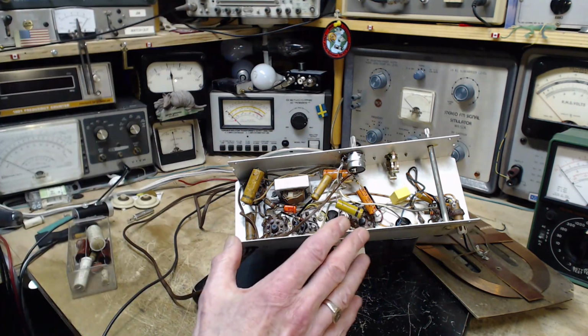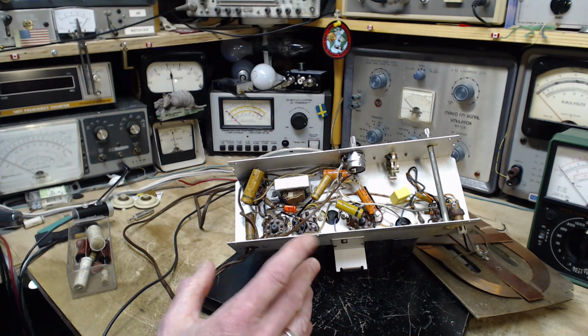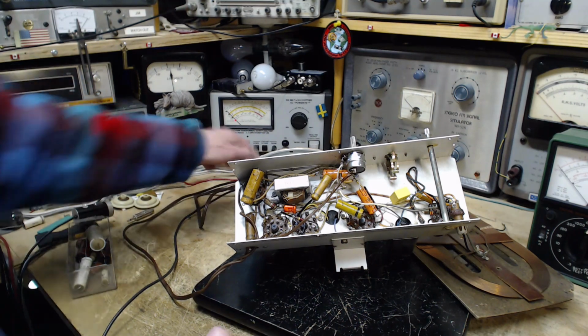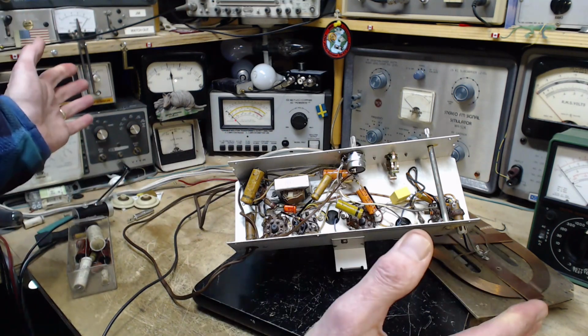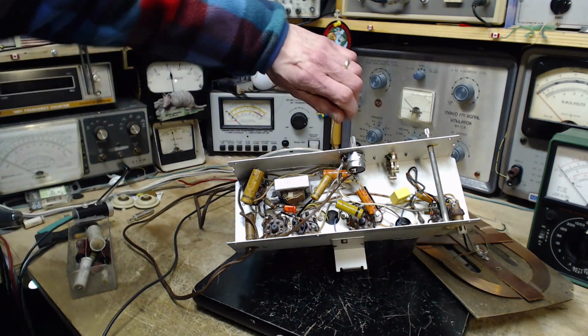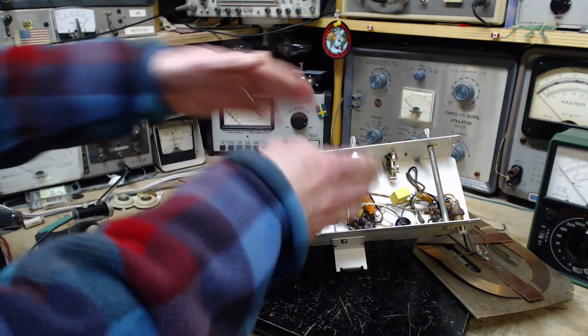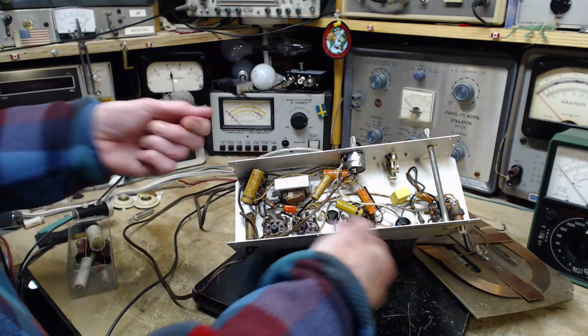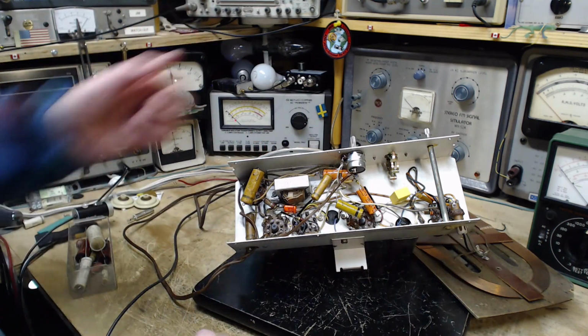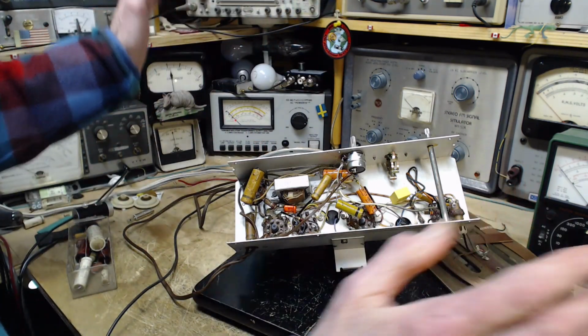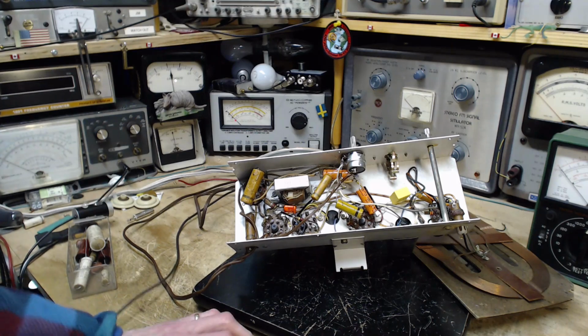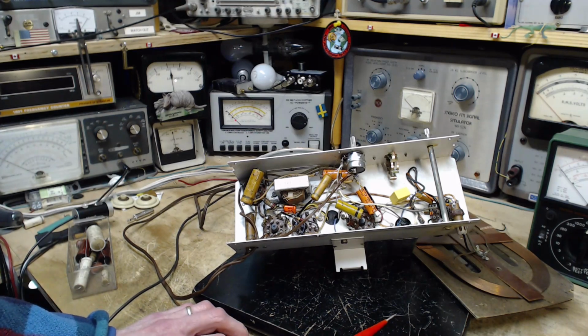That's the thing about these radios, is you may think you've solved the hot chassis problem by plugging it in and making a measurement. Okay, it's not hot anymore. Then you turn the set off and look out. The other way around, got the set turned off, move the plug, read the voltage. Good, no voltage anymore. Turn the set on. It's over. It's hard to escape the hot chassis problem. Very hard.